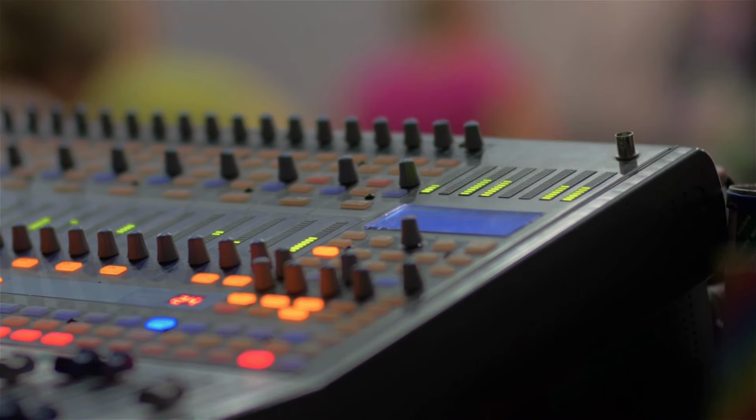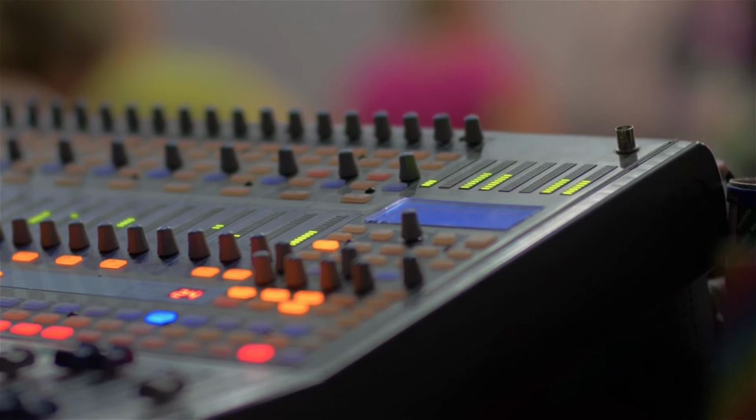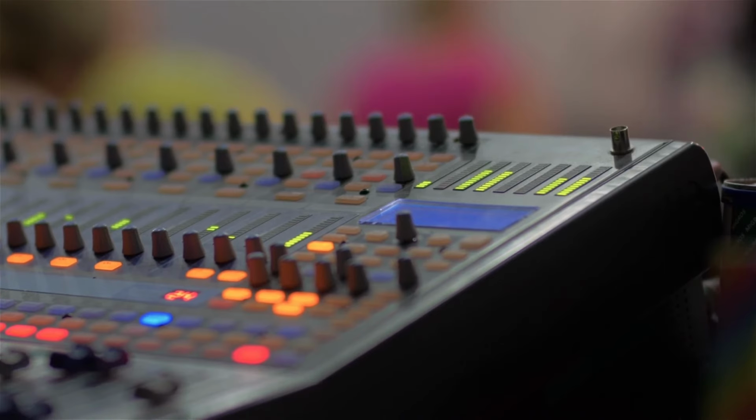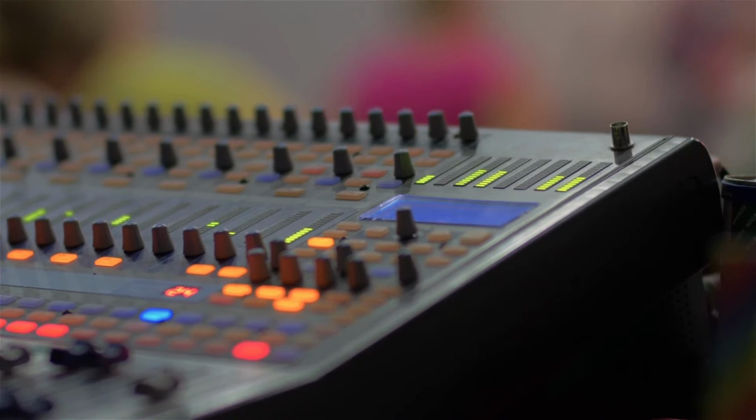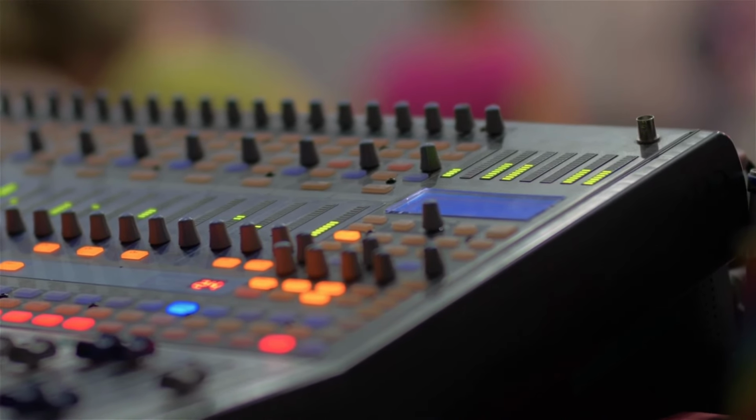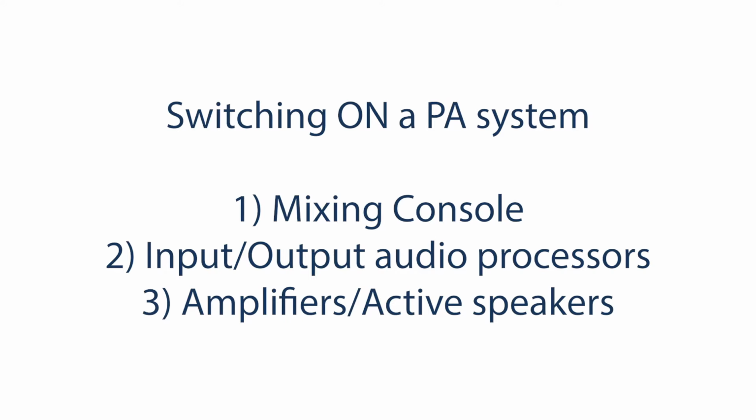You may have noticed that this was all done with all the equipment turned off. This is on purpose and for safety. When switching on a system, I would recommend switching the mixer on first, then the input and output audio processors such as any vocal processors or crossovers or speaker management systems, then lastly the amplifiers, or if the speakers are active, then the speakers themselves.